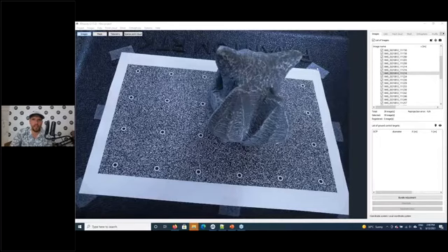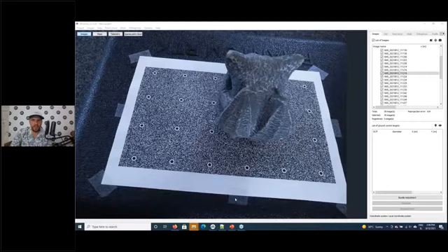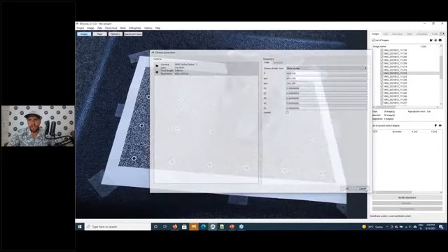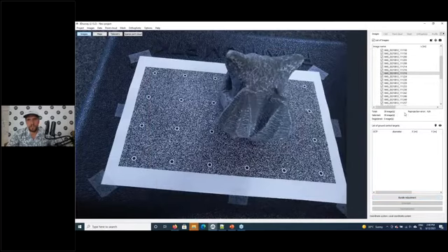So I taped the calibration field on a box. This is actually a drone box, so that it is flat and easier for me to record the photos. Now the first step would again be bundle adjustment. Here again, the initial values are not very accurate. You see here it's set by default to 4000. Then the first step would be to run the bundle adjustment on these 40 images because the initial values are pretty bad. So the first time the bundle adjustment will probably take slightly longer.